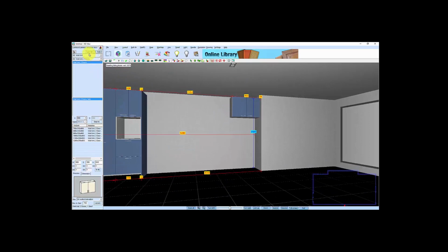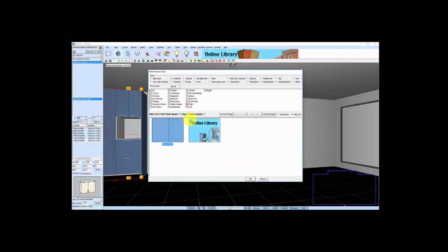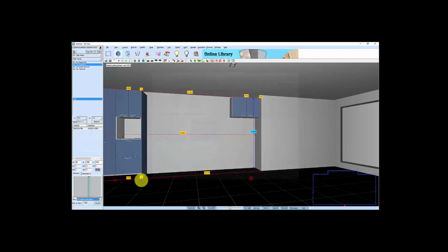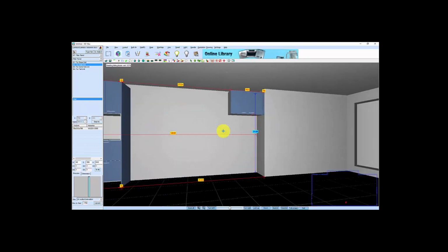What I'll do from there is I'll go Type Select, wall unit, I want an end filler panel, go to filler, go OK, go change that to 40, keep it at 350, 640 high, and I want it at 1760 off the floor. Press layout, drag it there and butts it into and just go no. So there's my filler for there.